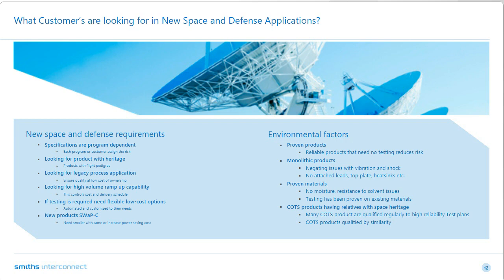COTS products with reliability relatives with space heritage can also be key in the decision-making of products used for LEO satellites. Many products have been qualified regularly to high reliability test plans and can be purchased in the COTS format of non-tested product. In areas where qualification is needed, COTS product can be easily qualified by similarity to ensure some level of reliability that, again, is good enough.